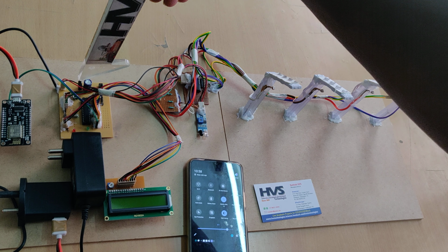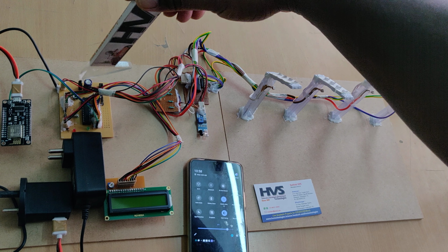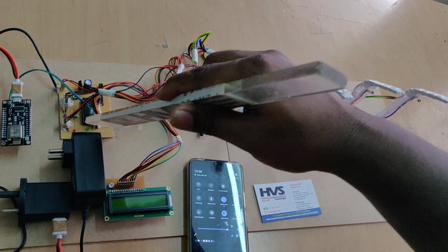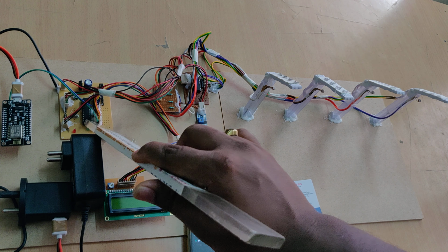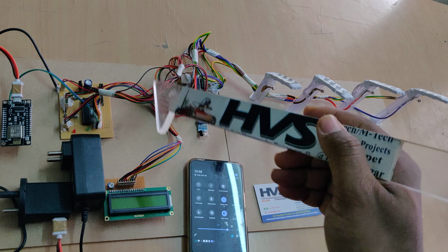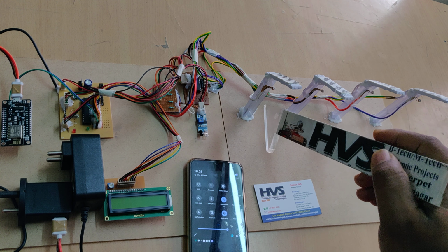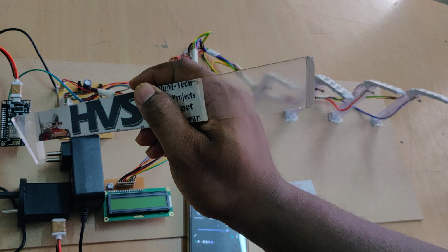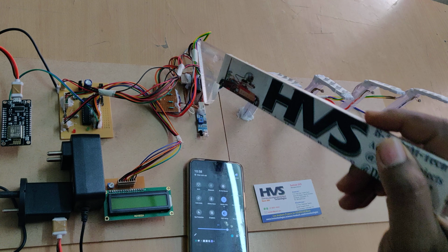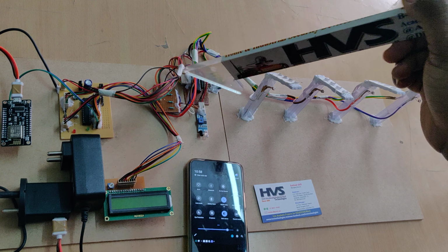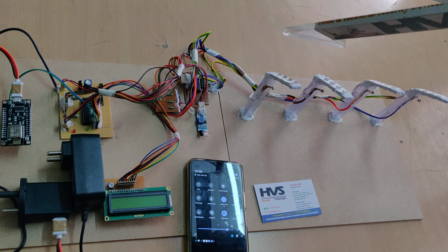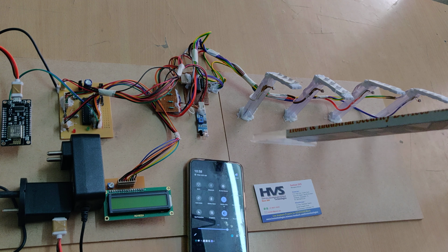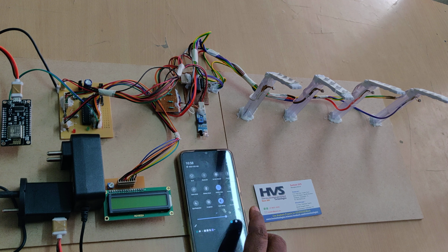For the microcontroller, there is one 7805 regulator, and after this we get the 5 volt regulated power supply, which is given as the main power supply source to the PIC microcontroller. Once it gets the power supply, it starts reading inputs from the IR sensors and LDRs, as well as driving the output street lights, LCD and Node MCU. So whenever a person enters, we turn on the street lights, the status is displayed on the LCD, and intimation is sent to the Blynk app through the Node MCU.